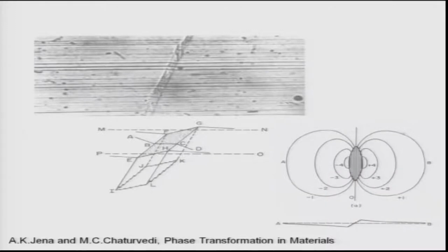See, if you look at the orientation of the plane E, F, G, H, that is bent in the same direction as the distortion of the crystal. So, that always happens, that means a distorted plane becomes an even plane, and a distorted direction remains a direction, even in the parent crystal, austenite crystal, as well as the martensitic crystal, they do not get changed. So, that is only possible when they keep the orientation relationship constant without distorting much.